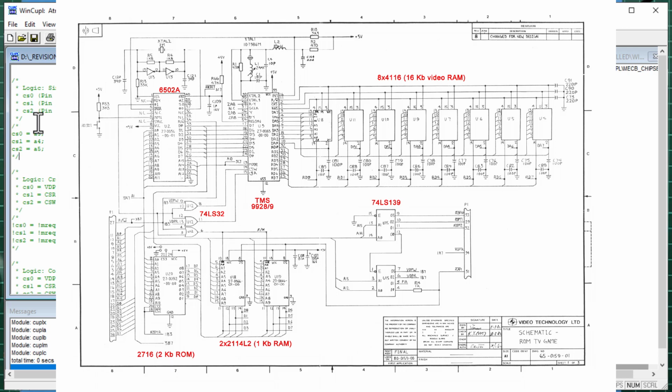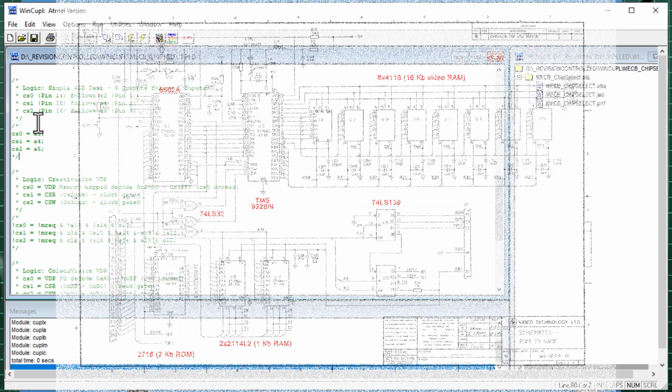Of interest, this simple address decoding circuit didn't gate in the 6502's read-write signal. This relied on the system programmer ensuring they didn't issue a write command to the 2000 address block, as this would cause a bus driver conflict, with both the CPU and the VDP data bus drivers simultaneously attempting to put data on the bus, potentially overloading the drivers of either the CPU or the VDP chip.